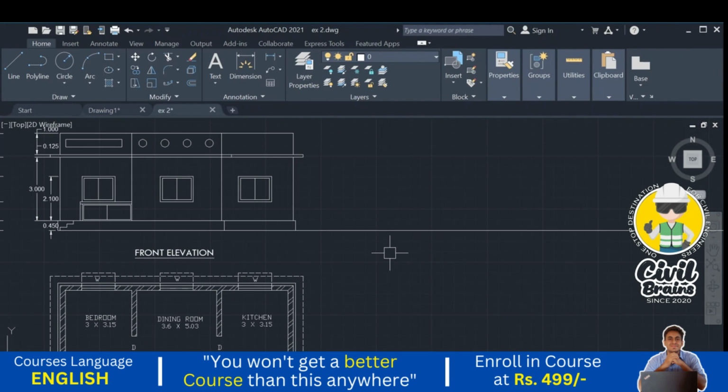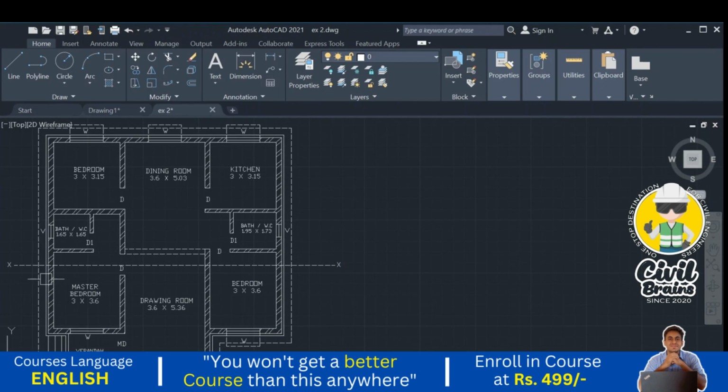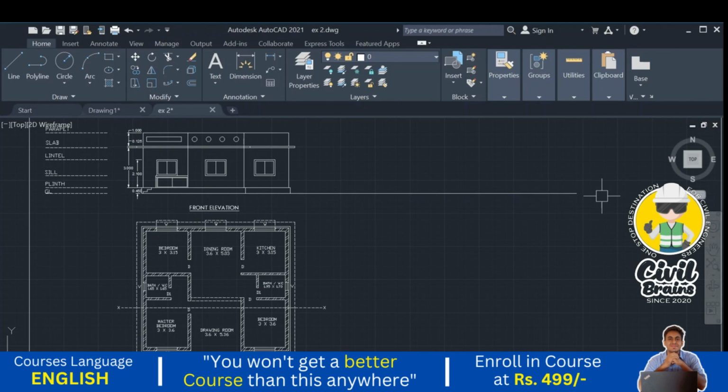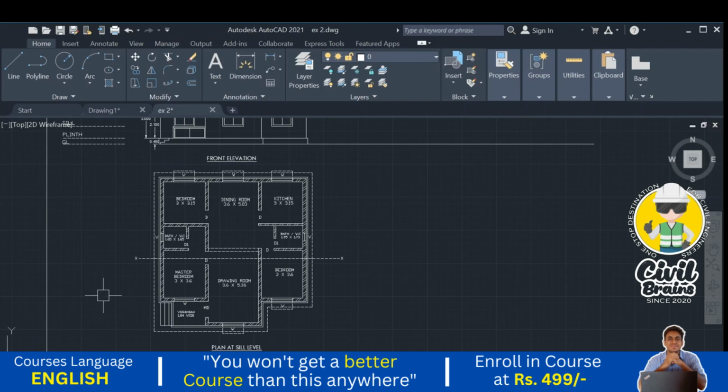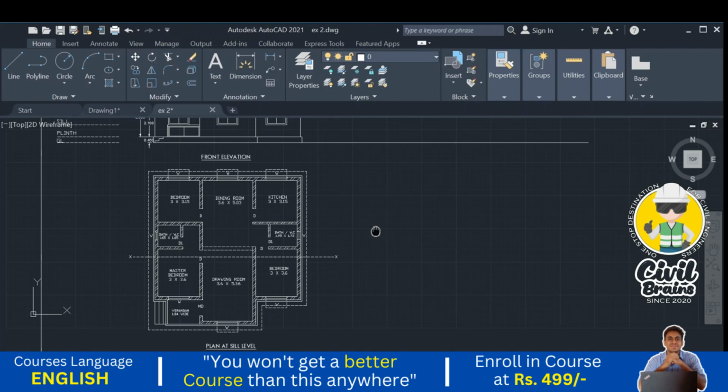Okay, so here where we need to draw this section, or the foundation below the wall, correct? So which walls? 1 2 3 4, whichever the cross section line is passing, those sections of the walls we need to draw. So how to draw that one? The first step is we need to draw the ground level. Next step is we need to mark the center lines of the walls.